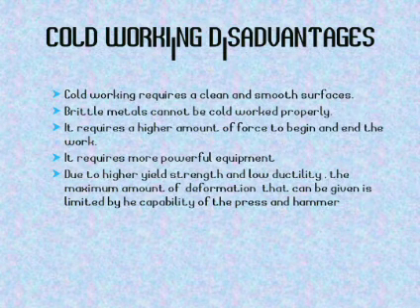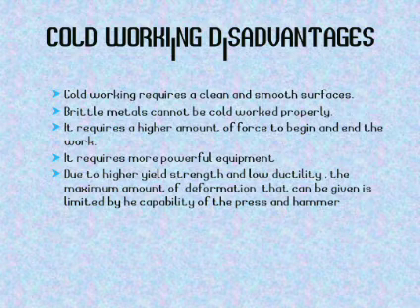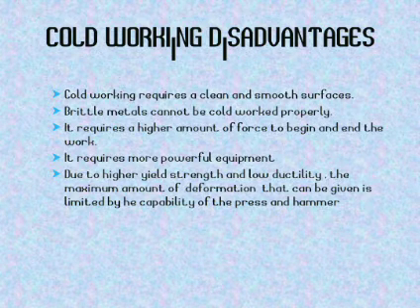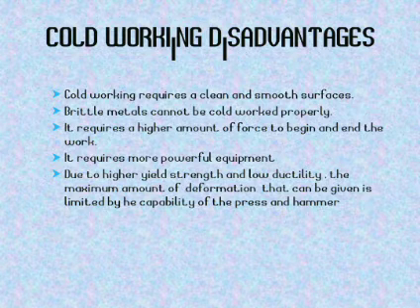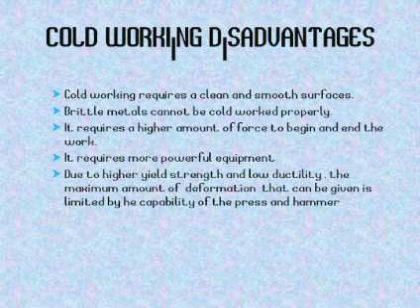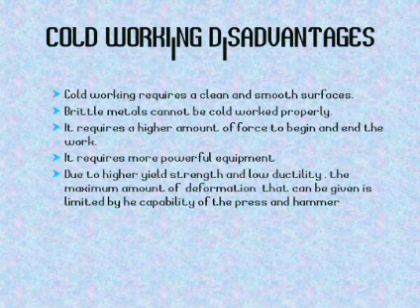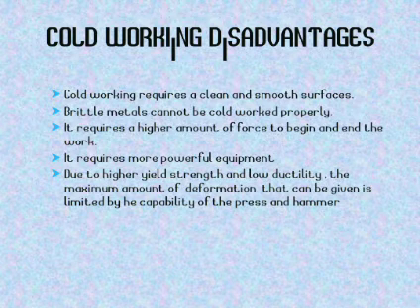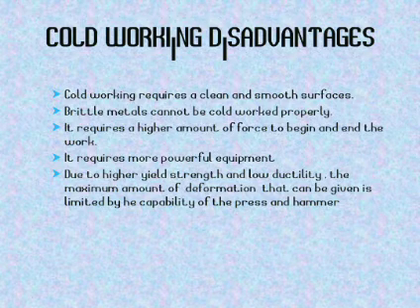We will also have the cold working disadvantages. Cold working requires clean and smooth surfaces. Brittle metals cannot be cold worked properly, and it requires a higher amount of force to begin and end the work. It also requires more powerful equipment, and due to higher yield strength and low ductility, the maximum amount of deformation that can be given is limited by the capability of the press and hammer.